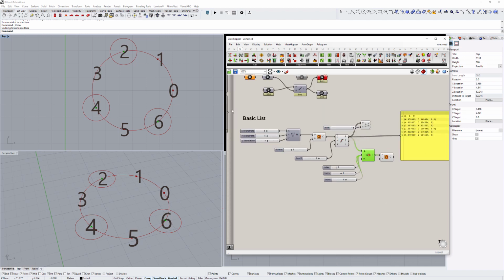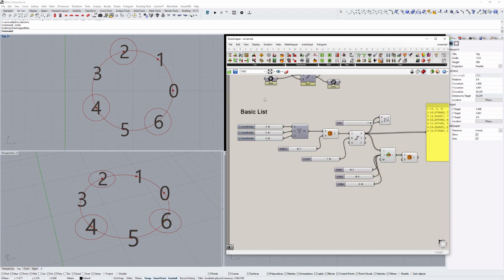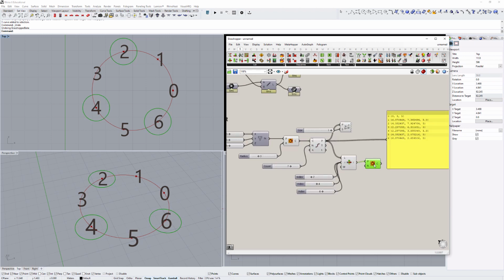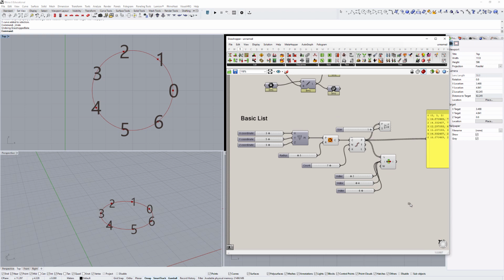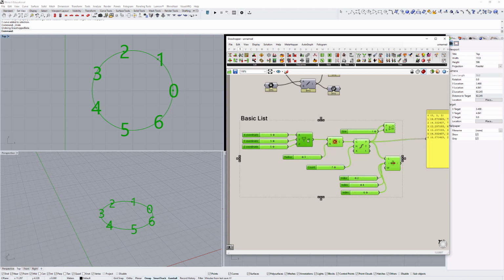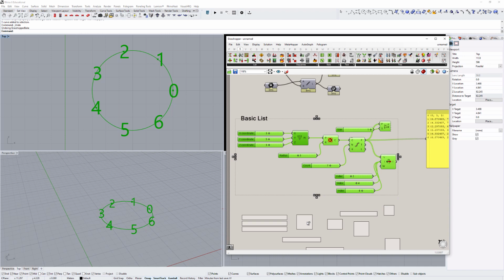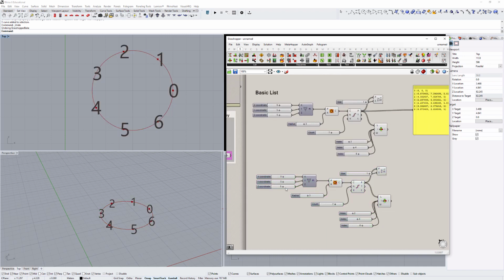Working with this first definition that we've created, I'm going to now ask you to delete that. I'm going to get you to select everything, click on one of the components of the green, and then while you have your left mouse button down, press Alt and drag to make a duplicate, and then change your Z coordinate.